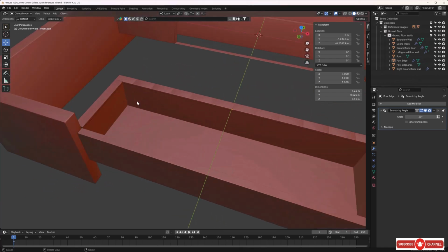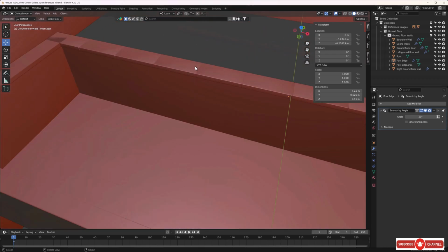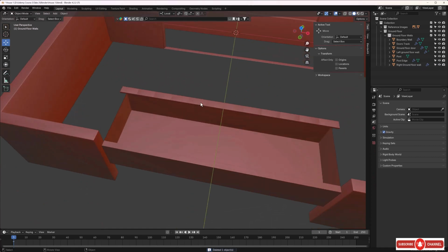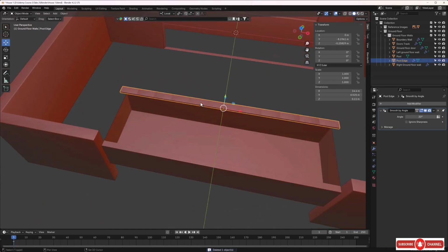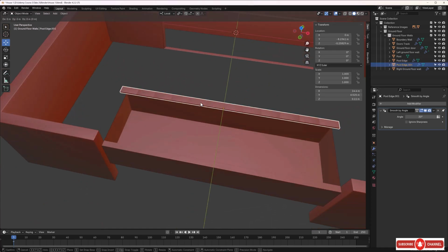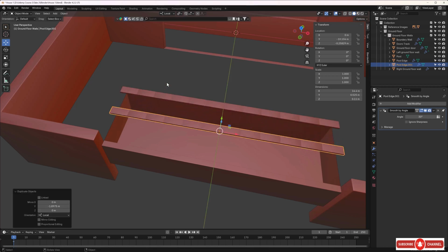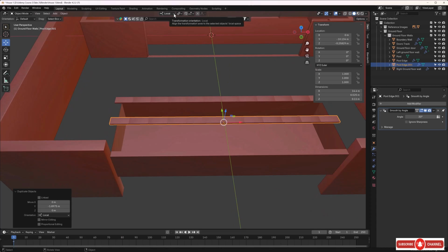I think what I'm going to do is, rather than use this piece here now, I'm going to make duplicates of this long piece here because we already have all our nice grooves in it. So let's utilize this. So I'll just go ahead and delete this one. And I'm going to make a copy of this, so I'll press Shift D and Y and bring a copy over like this. And let's go ahead and put our orientations back to global, and here as well on our pivot points, let's put that back to median.